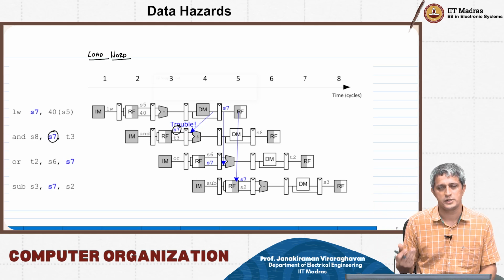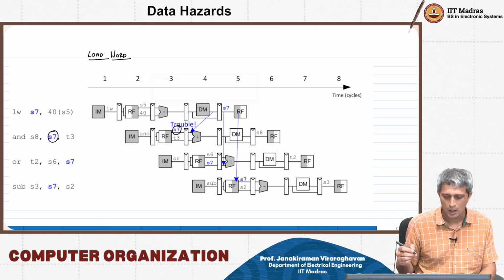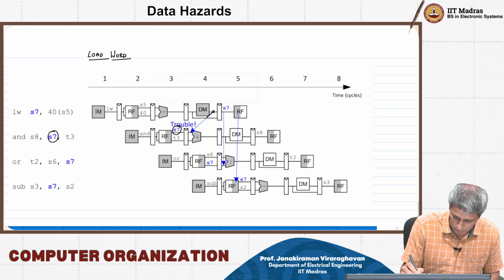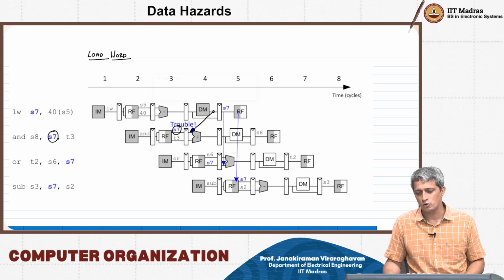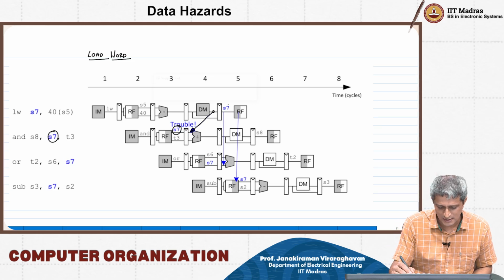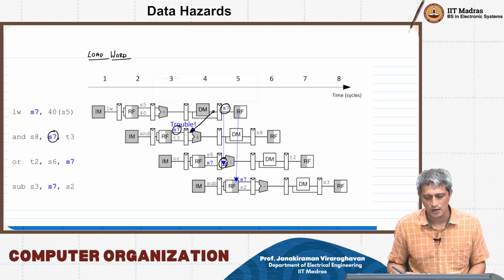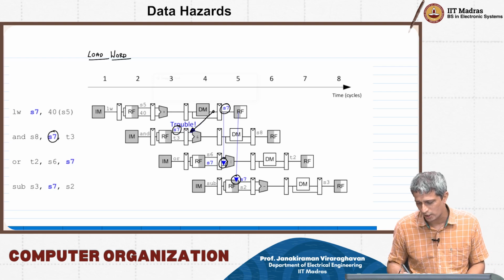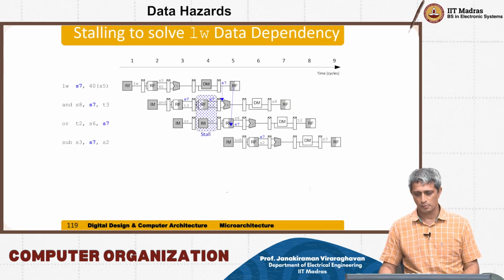Now, of course, just like we did the case of the register forwarding, what we basically need to do is that once you read the data memory output, it is already available here. So we have to find a way by which you can feed that back to the ALU. The S7 on the other hand is just register forwarding. Data is ready, just give it. There is no conflict because of the clock, so there is no issue. So you need to augment your register forwarding and do something else about this other problem as well.